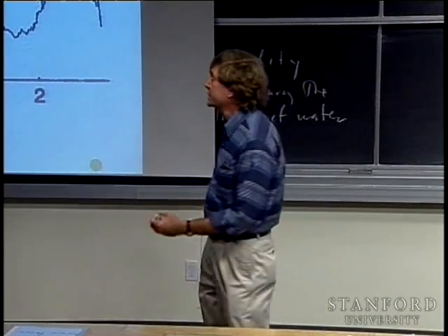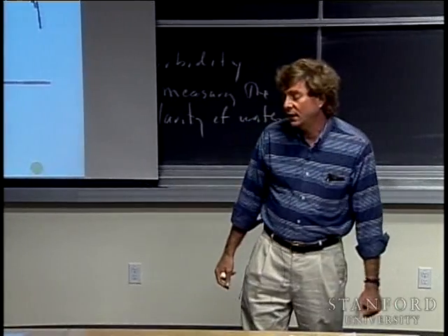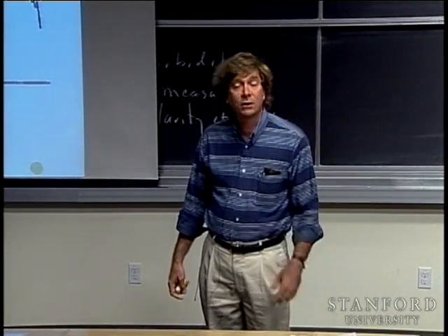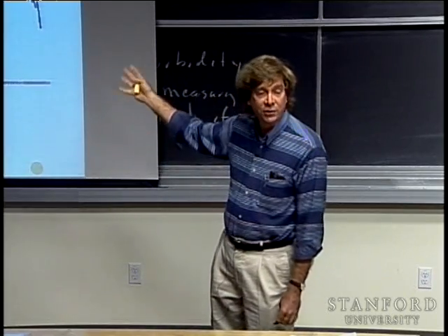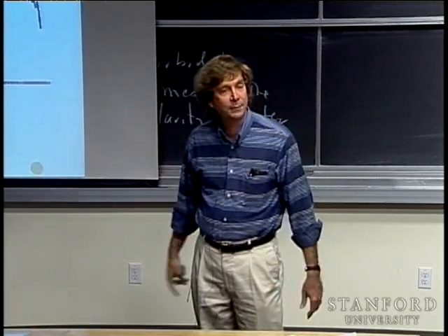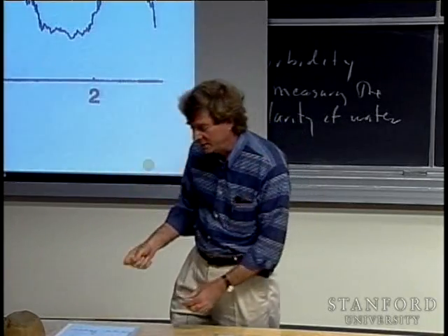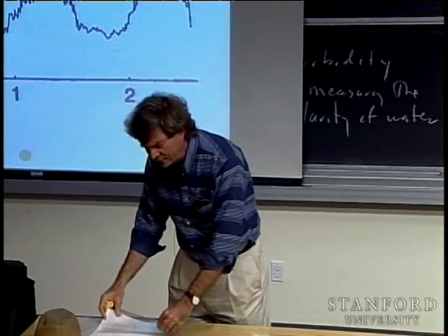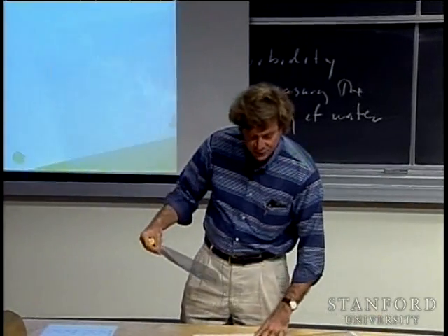All right? So the first step in the analysis, or in the smoothing of this data, is to take the Fourier transform. Now, in fact, the data is given to you in discrete form, so what you're actually taking is the discrete Fourier transform, and we're going to get to that shortly. But think of everything here as continuous, and think about taking the Fourier transform by whatever means you have. If you do that, you get a picture that looks like this. This is a picture in the frequency domain, a picture of the Fourier transform of the signal.